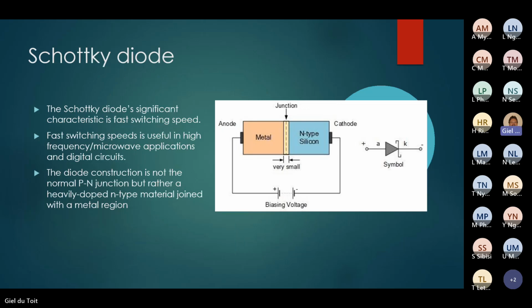The Schottky diode is not much different from a normal diode. It's always in forward bias, and a Schottky diode's voltage is lower, about 0.3 volts. The Schottky diode has a little symbol there that looks like an S, so that's how you can remember it, S for Schottky. That little curly line looks like an S. It's a very fast diode and it's used for high frequency applications. You can read it here. The questions in the test sometimes come out of these notes on the side, so you must learn and read through this.